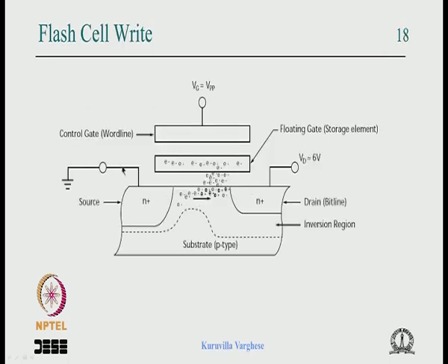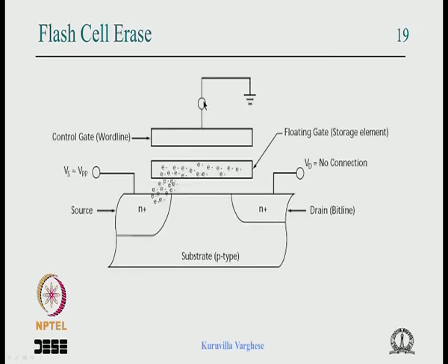So that is shown here. The source is grounded, the drain is given the supply voltage, and a higher voltage pulse is applied. So electrons tunnel and get in here, and then the normal application of the gate voltage wouldn't make the channel and it wouldn't conduct. And when you want to erase it, you do the opposite: you ground the gate, you apply a pulse here, and it gets out. So one advantage of the flash is that it can be programmed on or off electrically, and much more than that, if the chip has a port for doing that, within the circuit you can program it.